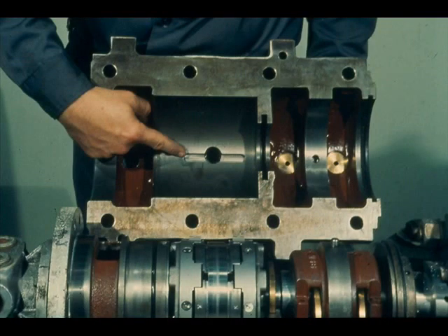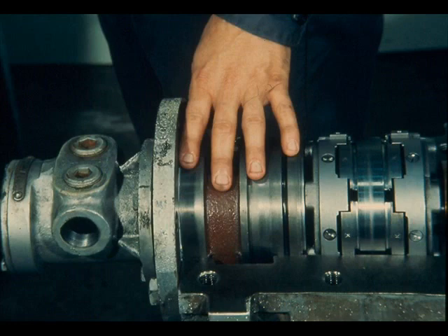Thrust bearings are laterally positioned in the bearing housing, with the oil pump bracket or housing end cap being pointed out here. A static O-ring here prevents oil from leaking through the fit between the pump bracket and the bearing housing.